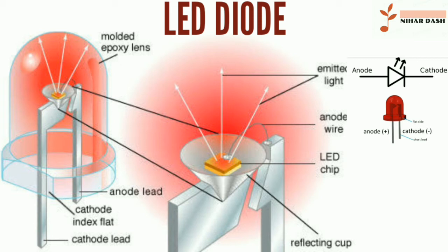LEDs generate visible radiation by the electroluminescence phenomenon when a low voltage direct current is applied to a suitably doped crystal containing a p-n junction, as shown in the diagram below. The doping is typically carried out with elements from columns III and V of the periodic table.